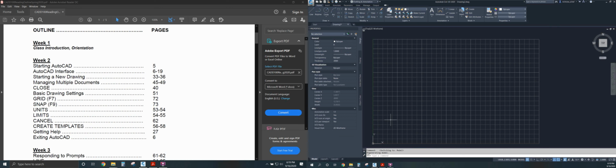If you press F7, that turns off your grid. The other way to turn on and off your grid, because I almost never remember to do F7, because in civil drafting you do not use grid, is this right here. This is grid mode. When it is highlighted blue, that means that grid is on. When it is not blue and it's just gray like everything else, then it is turned off. In the meantime, I'm going to leave mine on.